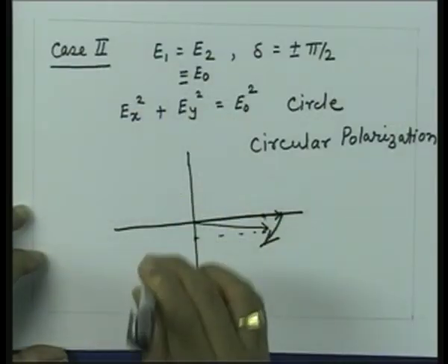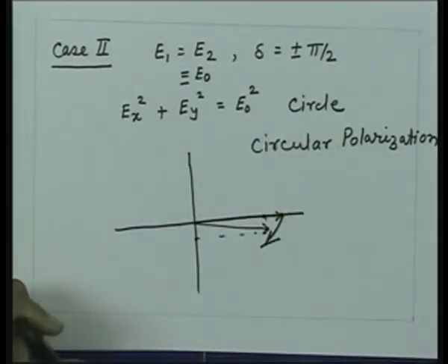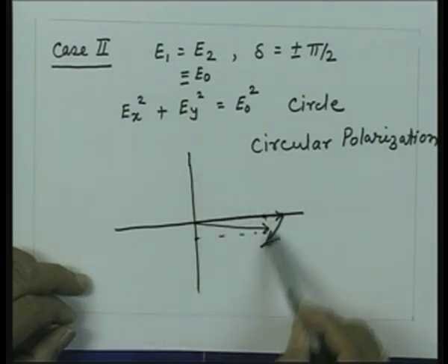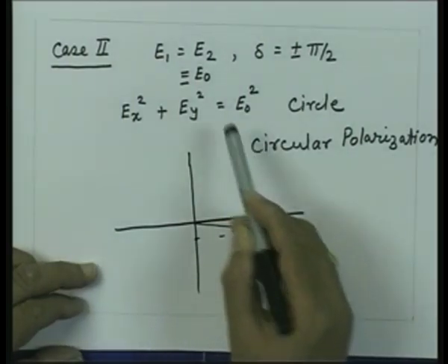So, what we do is we define the reference direction, that is the direction of wave propagation, which in this case is the one which is coming out of the paper, that is positive z direction. So, whenever we define the rotation of the field vector as a function of time, we take the reference x, y, z coordinate system, we assume that the wave is travelling in the positive z direction, and then we say that if delta is positive, we will have a rotation of the electric field vector which is clockwise, and it will be anti-clockwise if delta is negative.